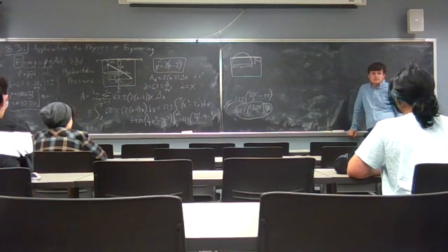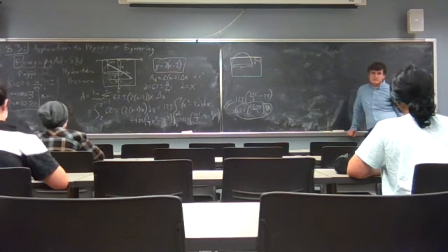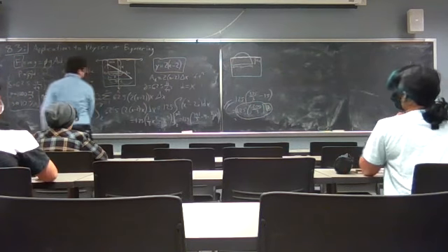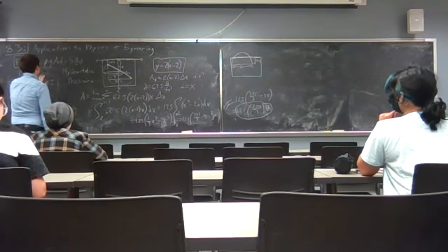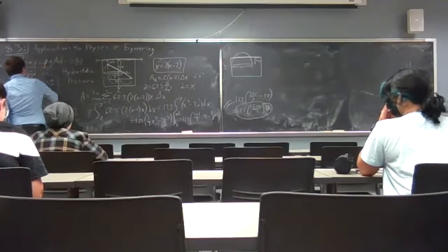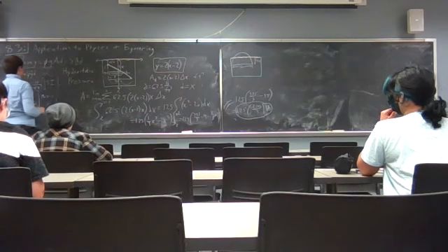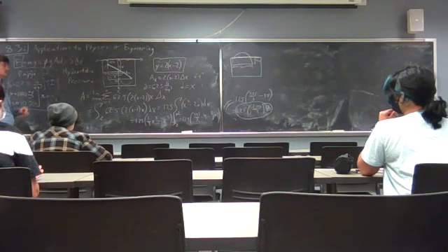Okay, so I understand that these are harder ones. Even when I come to these, sometimes we have to really just sit and work with it a little bit, think about it. But let's walk through what we did again. This is what I want to find, the force. So I need all of these things. Rho, I got it. G, I got it. Sometimes they're both together in terms of the 62.5, which was the case since we were in feet here. And then I need the area and I need the depth.